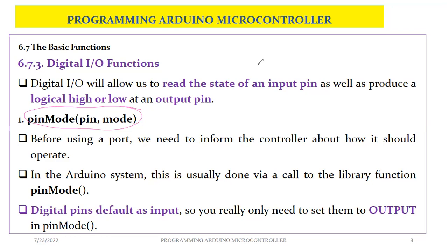For the digital pins, they operate as input pins by default, and therefore it is important that we specify the output mode in case we want to deploy them as output pins. But if we want to use the digital pins as input pins, it is not necessary to specify the pin mode, though even if you specify the pin mode, it causes no harm.